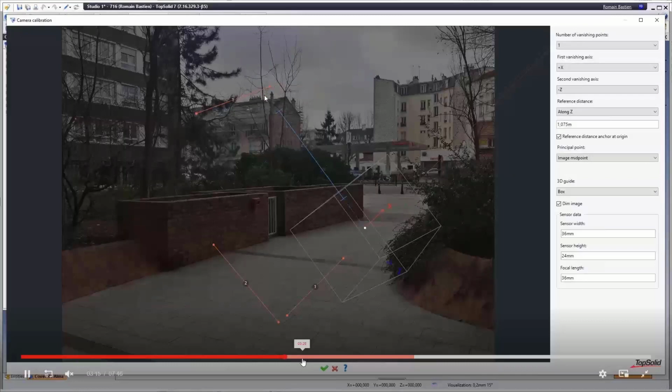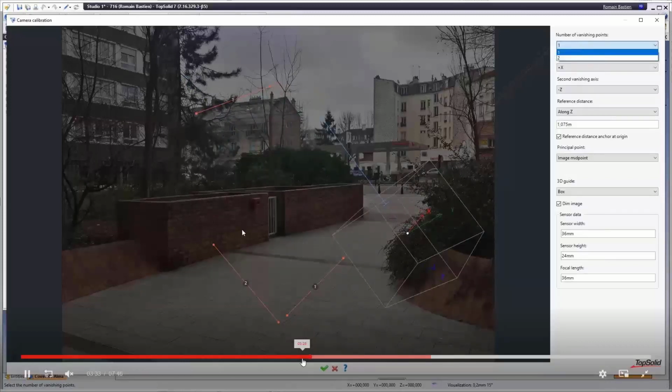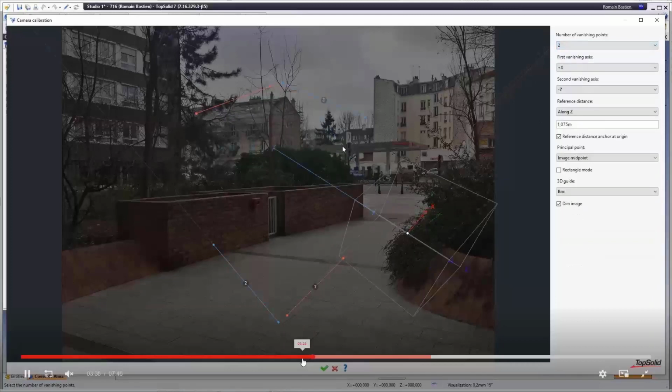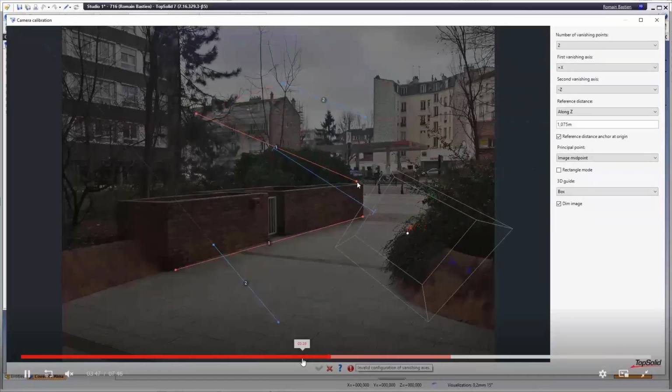Go. And now what's happening is we're basically using a specific tool, it's called camera calibration, to define where our zero reference is on this image and to define the orientation of the x-axis and the y or the z-axis, as well as a scale. Okay, and you can see here it's done just by dragging these objects around to define how everything is. And so this is the x-axis that we're defining right now.